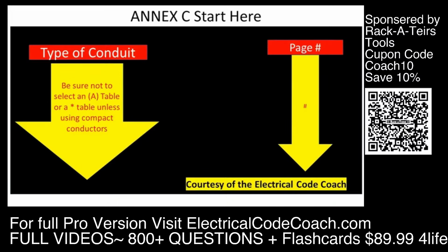The A symbol signifies compact conductors. There are several different types of conductors out in the industry. Some of them are concentric, but the ones that are compact are bound a little bit tighter, and you can actually fit more of those inside of a pipe legally. But for your normal pipe fill questions, they're not compact conductors. Matter of factly, unless it says the word compact conductors, you will never assume that they're compact conductors.